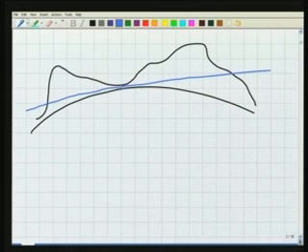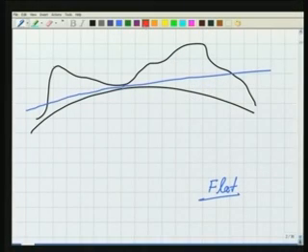Okay. Now when I say, let us consider the earth to be flat. If you consider the earth to be flat for measurement, what is the meaning of that? The meaning of that is, our points which are here, I am projecting those on the tangent plane.